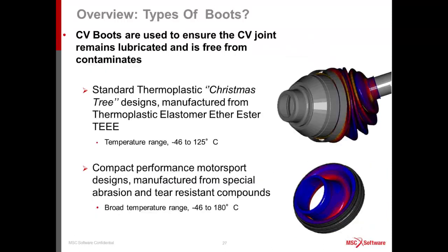There are two types of standard CV boots, what we call a Christmas tree boot, which is normally molded from a thermoplastic elastomer, which has a nice temperature range of about -46 to about 125 degrees C. For motorsport applications, we design using a special compound that we develop, which is very abrasion and tear resistant, and that allows us to work from about -46 again to about 180 degrees C. In motorsport applications, the deformation angles are a lot smaller, so it means we can compress the design quite significantly.